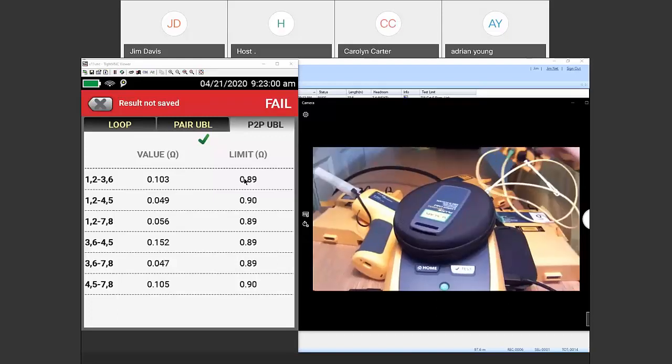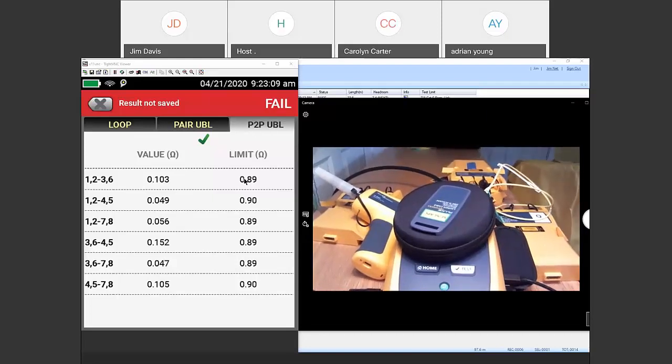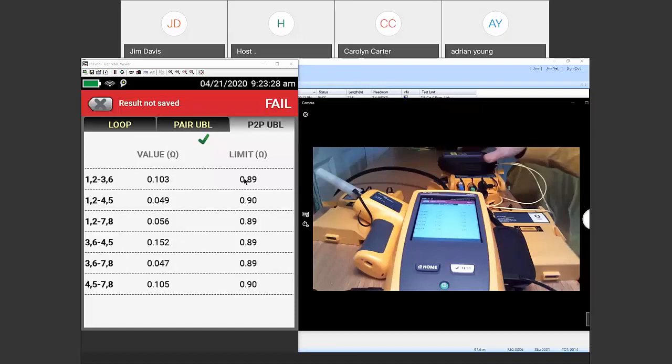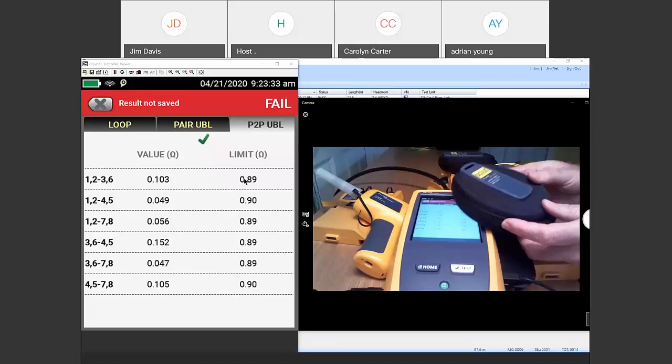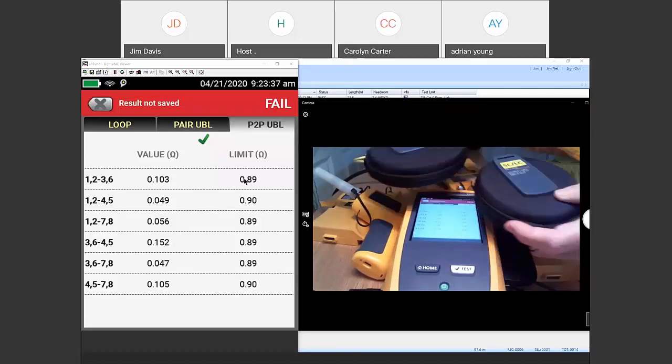Sure. From last week's webinar, we saw that the launch pack, or the dead zone eliminator, is a length of fiber that we use to be able to measure the first connection. If we need to measure the first connection that a fiber is making, then we use the launch pack to eliminate the dead zone that happens on the port of the OTDR. The very important thing about your launch pack is that it has the same type of connectors as what you have on the wall.